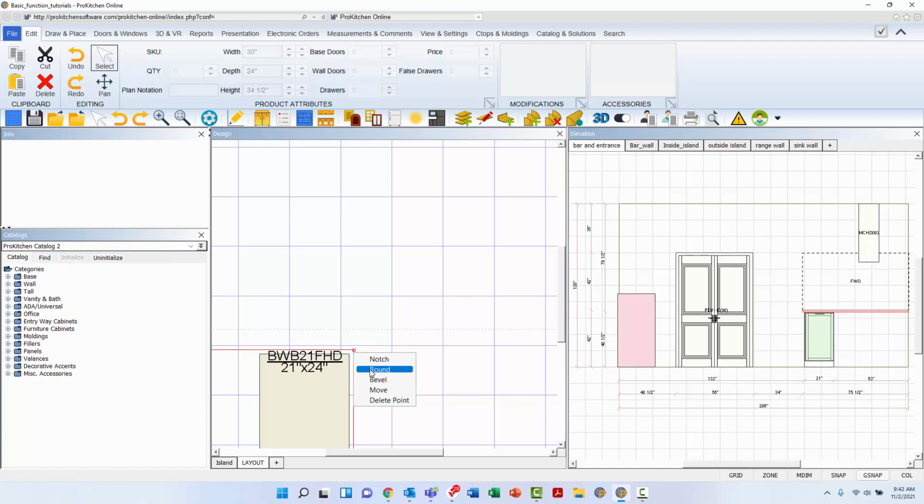Once you left-click to select, you may once again only create the rounded corner to the interior. As you move the mouse, you will see a preview of the rounded corner. Drag the rounded corner into place and left-click to secure. Once created, you will now have 2 points on either side of the curve that, when selected, will change the shape of the countertop, and a center point that will allow you to adjust the curvature of the rounded corner.